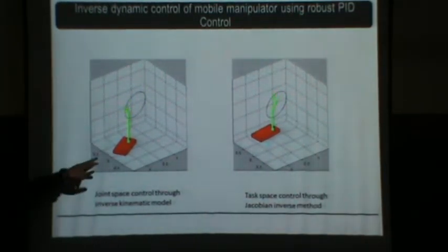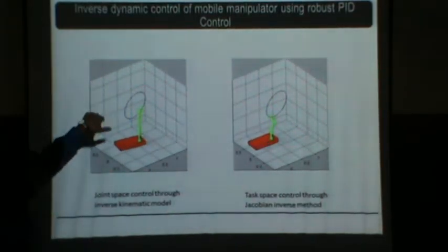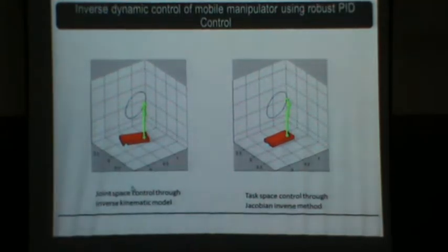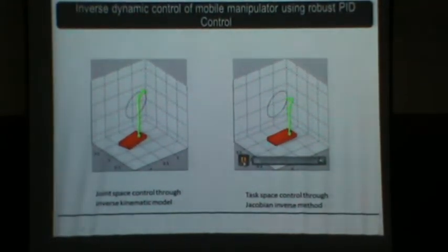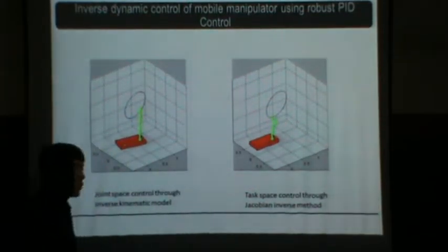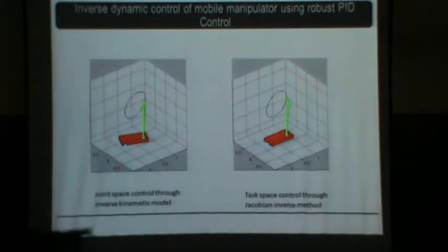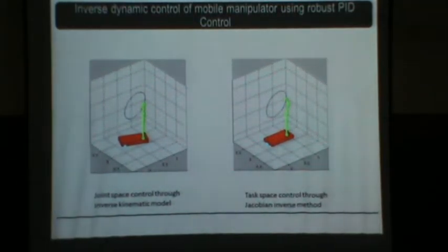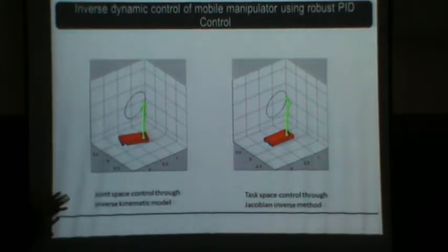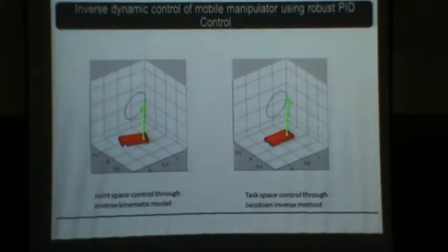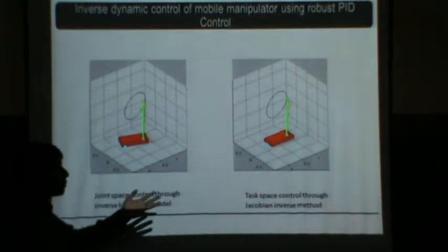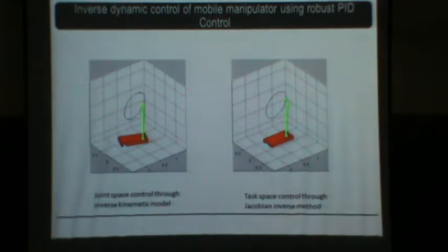You can see that this is giving inverse kinematics in such a way that the vehicle's entire motion is there. But here you can see that the vehicle is not much involved. So you can see once again the difference between the vehicle motions. Obviously here the less inertia, which is the manipulator, is involved more. In this case even the vehicle and manipulator both are involved, because one of the inverse kinematics solutions is like that. You have to find which is the global minimum and take that. But if you take an initial guess bound to a local minimum, then you end up with a local solution. That solution may not be optimal. But if you use task-based control, it is automatically adjusted. That's what we are trying to show.